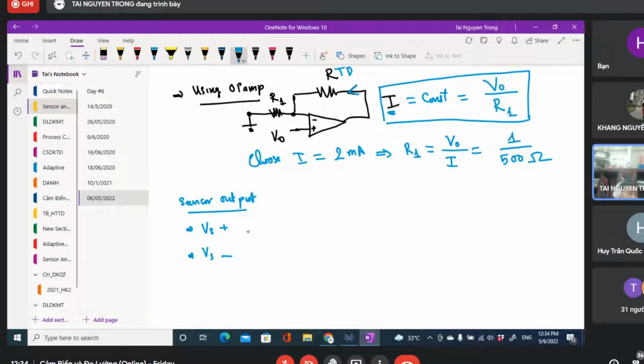Calculate KC from the first step, then we multiply KC with the original system to obtain Z sub 1. And now we draw a Bode diagram of Z sub 1. Remember, it is Z sub 1, not Z of S. For step 3 and step 4, we determine the gain crossover frequency and the phase margin. You should be very familiar with these steps.